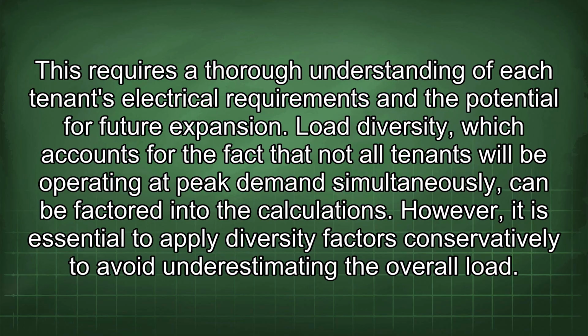Load diversity, which accounts for the fact that not all tenants will be operating at peak demand simultaneously, can be factored into the calculations. However, it is essential to apply diversity factors conservatively to avoid underestimating the overall load.